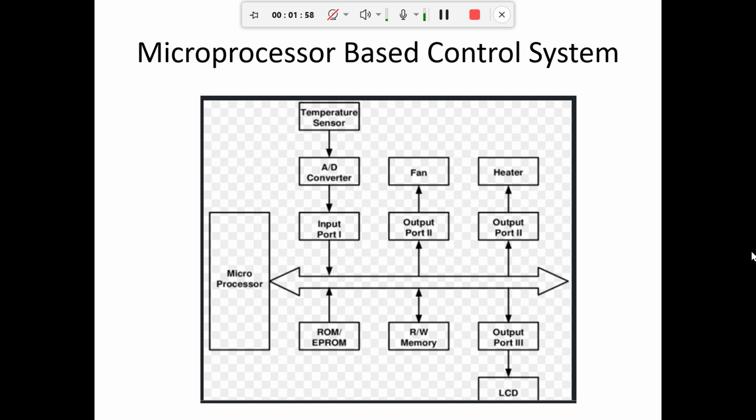Similarly, after doing the process, you have to save the result. Where will you save the result? You will bring the result back into the register. That's why we basically require registers to hold the data. The data we give to the ALU is processed according to the requirement, and the result of the process is stored again in the register.